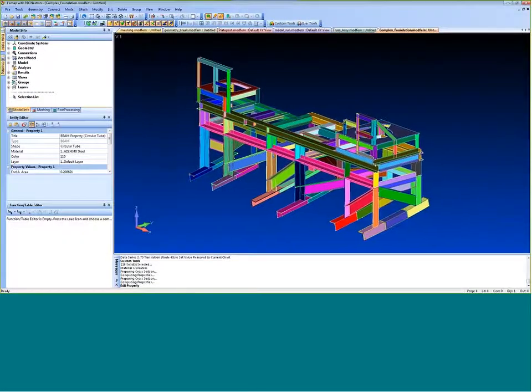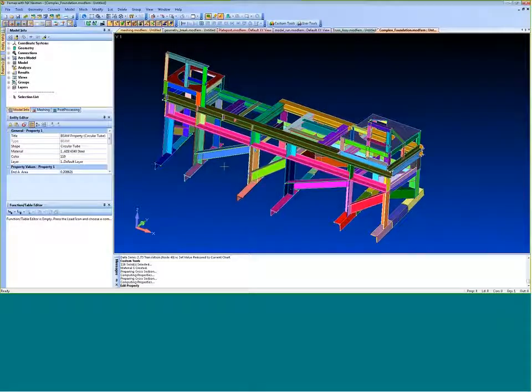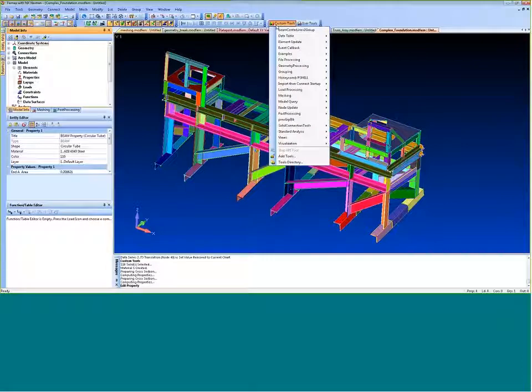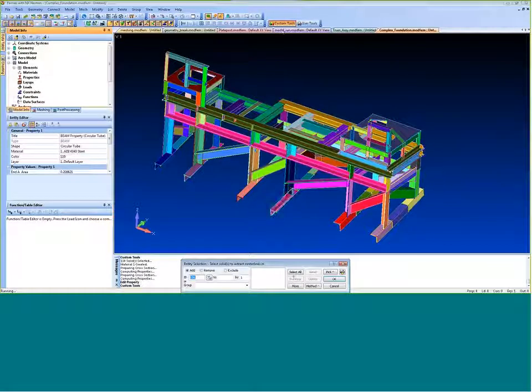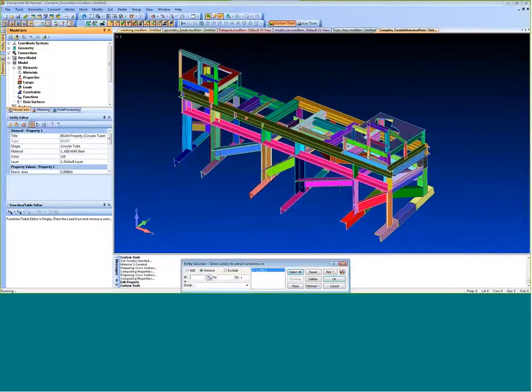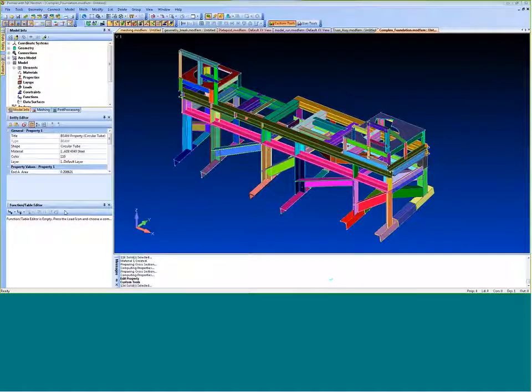Now I'm going to show another example of this API, but this one is for a complex geometry that doesn't really have any tubes. Once again, nothing is defined in this model yet, but we do have hundreds of solid bodies. I'm going to use this tool again. Here, I actually don't want to extract center lines for all the geometry because not all of these are beams. I'm going to do all at first, but then get rid of the ones I don't want, namely these two plates here. That way I can select only the geometry I want. Do OK.